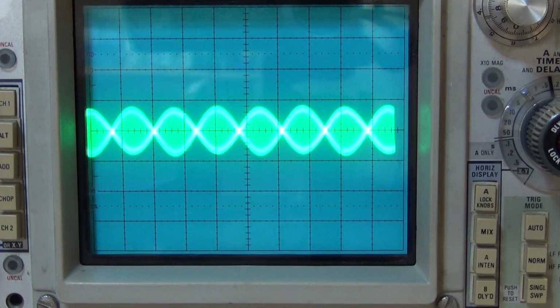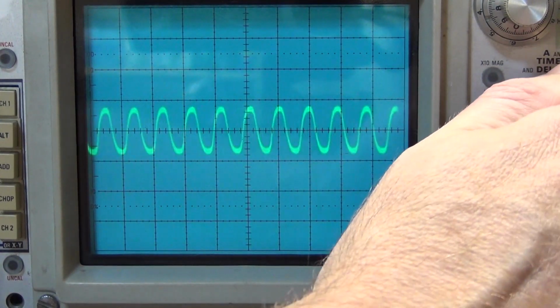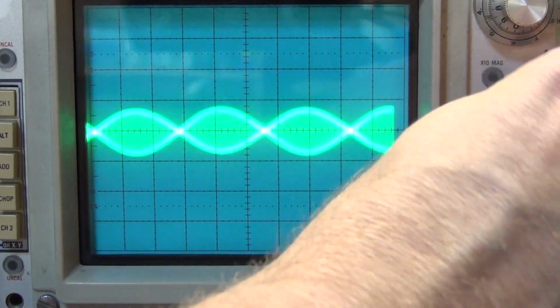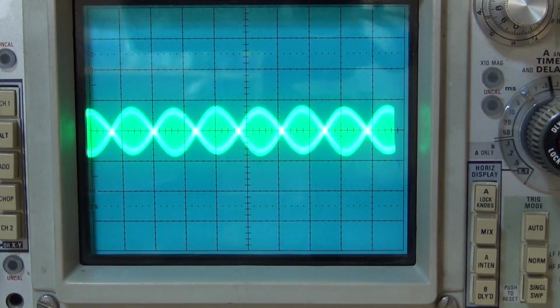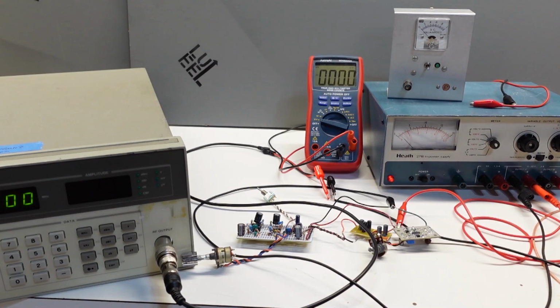And just one last little interesting thing, if you set the time base even higher on the scope, you can actually see the baseband frequency there. That's the 5.5 megahertz RF signal, and it's being modulated at 2 kilohertz by the double balance modulator. I do have one more measurement I want to do here on this balance modulator, and that's a more direct measurement of the output power.